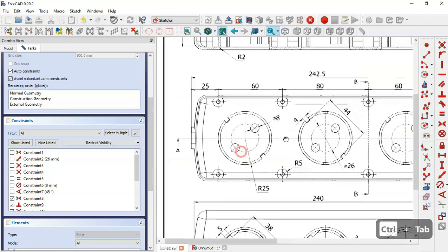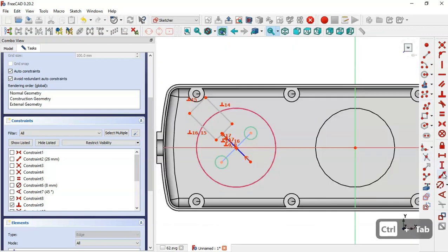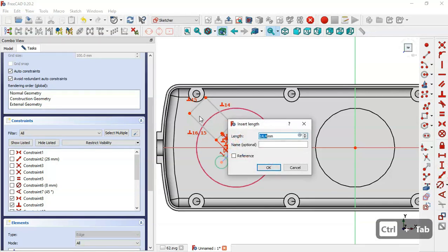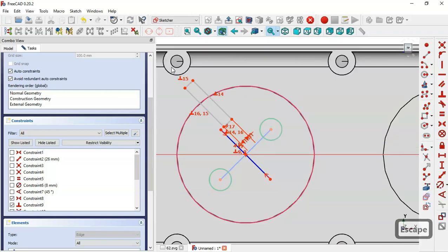And now here we'll set the dimension of these rectangles. So here we have 4 millimeters. So we select this constraint here and we set 4 millimeters for this line here. And now we select this rectangle here and we go to this option, clone, and now click in this point here and we get this rectangle. And next we select these 2 lines and we set equal.